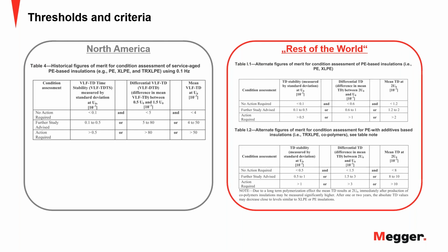Maybe I can add to this. Thank you, Marshall. This reference that Marshall is talking about is contained in the IEEE 400.2 standard. There is a section about tan delta testing and limits and evaluation criteria. And many machines today, when you measure tan delta, have these built in, so they automatically compare the test results directly against the table from IEEE and give you an answer, you know, what's required to do with that cable.